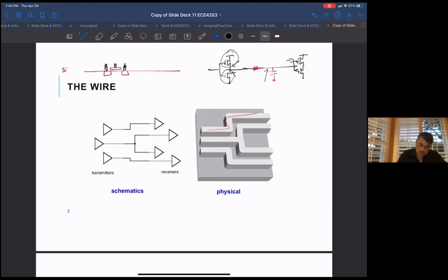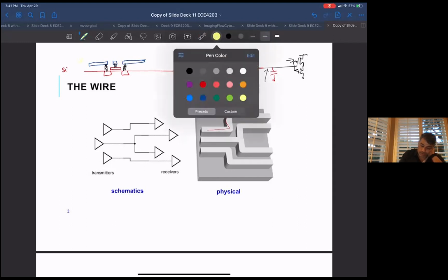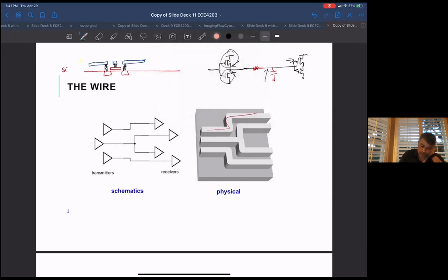And then you would have some metal layers, metal one, something like that. And then you'd need some kind of a dielectric layer, where that doesn't show up very well. Let's do pink. So this would be another oxide layer that you've deposited.